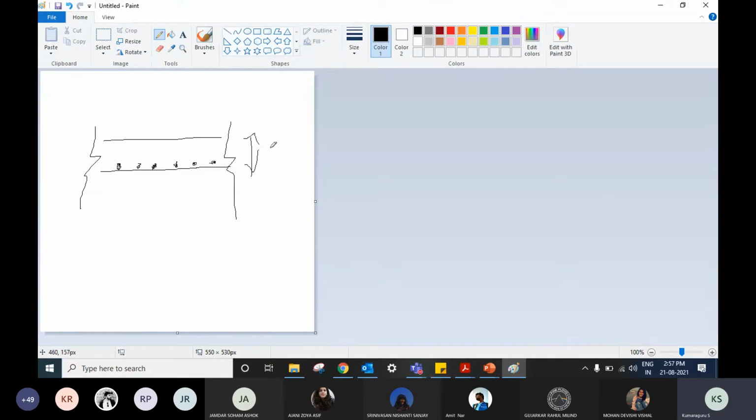So if this is the D. Now, why I told you this: only these reinforcements are carrying the tension, and there's something called the neutral axis, NA. Above it you have compression and below you have tension. In the tension zone, the concrete is not contributing anything at all. Only the steel reinforcement bars experience the tension and carry it. Anything above the neutral axis is where your concrete is effective. What I mean by effective is that your concrete is stressed here, because it's in compression.